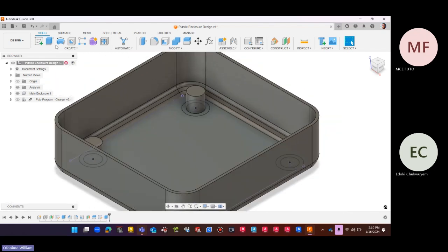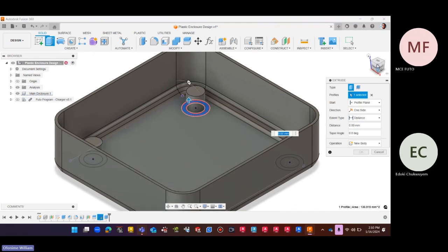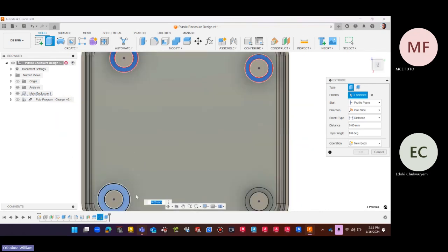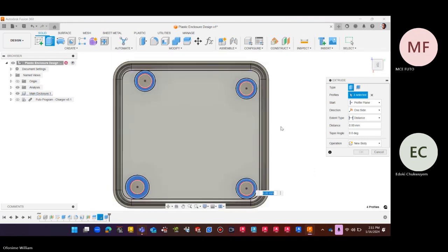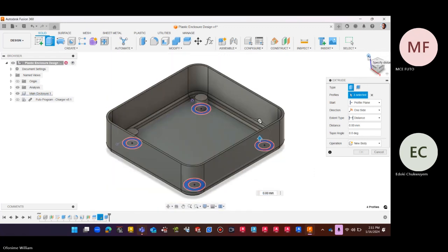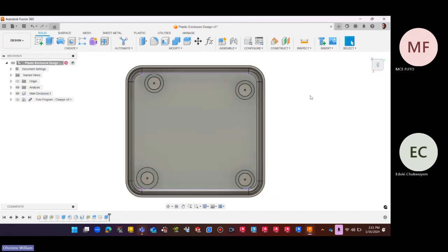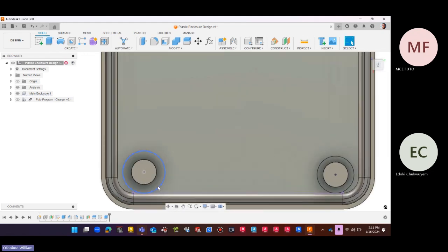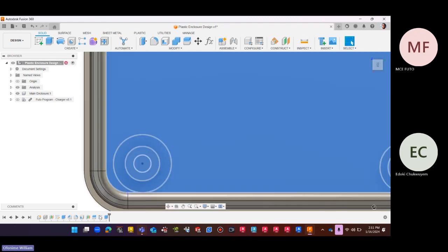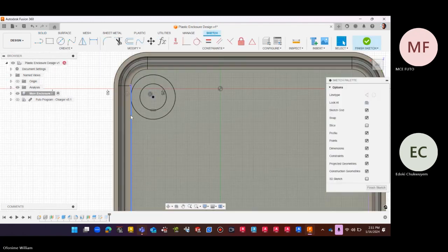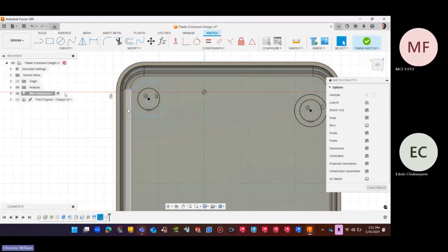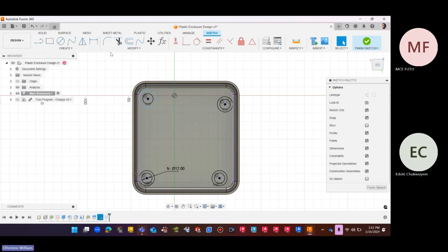So we just come over and then say another extrude. You still leverage the same sketch. I just noticed something as well. If you're also observant, it seems this other one is also a little bigger. So let's click edit. Probably remove these constraints and also use an equality. You of course know why it's looking that way. Like I said, it's not symmetric. So say equal. So still equate this to this as well.